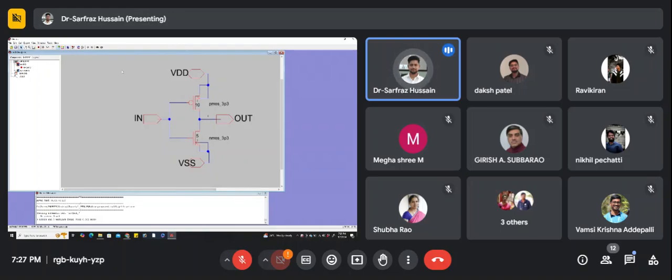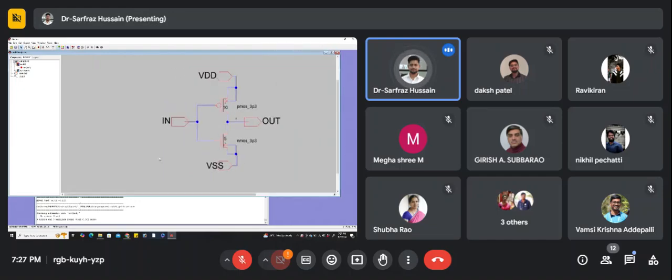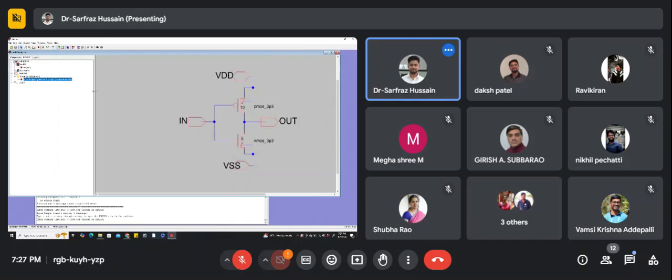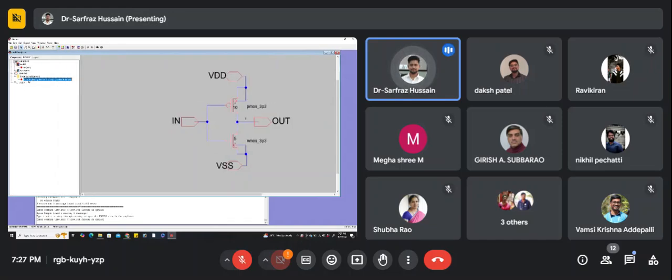So this is how we can integrate LTspice with the Electric software. Now I want to run the simulation for this. I go to Tools, then Simulation (Spice), and click on Write Spice Deck. When you click on it, your LTspice should open, but here I'm getting an error. You might get this error too. The error it is showing is error opening inverter.spi, access is denied, right?